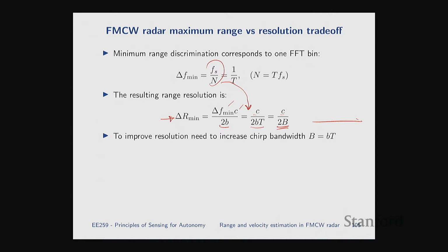And remember, the bandwidth of the chirp is, if you look at this frequency versus time, if you go from fc to fc plus slew rate times T, where T is the total chirp duration, this is our chirp bandwidth B, which is slew rate times the total duration. This is exactly the same expression, by the way, we got for CTFM sonar. No changes because it's the same principle of operation, same algorithm, so it makes sense that you get the same type of performance out of it.